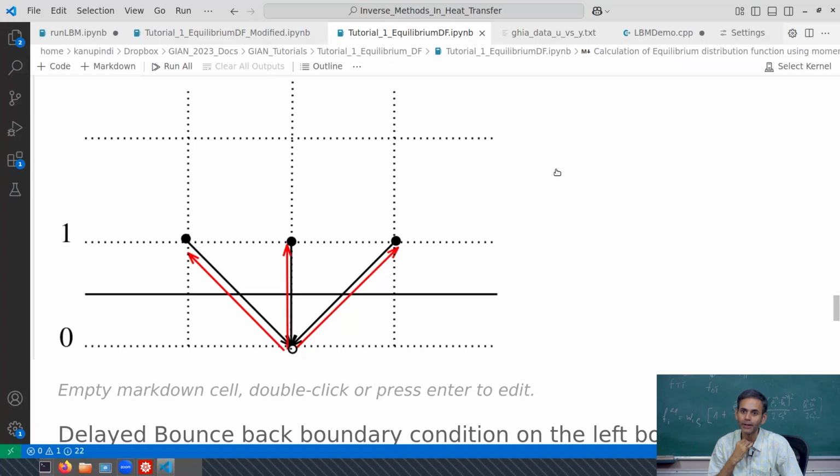Otherwise, if I am populating my zero values as the boundary values, then I should keep in mind that the distance between 0 and 1 is actually not delta x, but it is delta x by 2. It is uniform for everybody else, but for the penultimate to ultimate it is only half of what it is. Correct? Because it is not uniform at the boundaries. That's what I have to keep in mind if I'm going to use the same zero values to populate the u x, u y and rho.